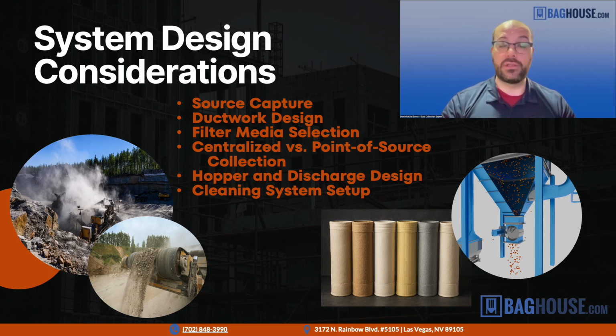A few things with ductwork design. Ductwork in general is the thing that takes the most amount of engineering and time when we're designing a system. People think it's the baghouse or the dust collector, but often I'd say 80% of our time and efforts go into designing the ductwork. And a lot of the problems that happen in older cement and mining plants are because the ductwork over the years gets changed, modified, neglected. And each time it's changed a little bit or repairs are done in a less than ideal way, it's the death by 1,000 cuts. And that's how you end up with a lot of the problems at these facilities, because the ductwork is not ideal, not so much the baghouse.